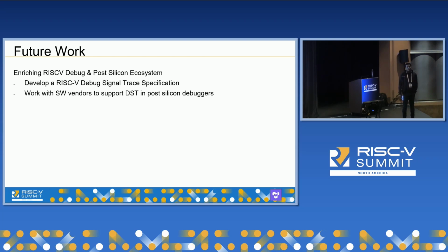But additionally, it also depends upon what compression logic you are using, right? So when we looked at the debug bus signals which are selected, we had three profiles: a profile with very active traffic, a profile with medium traffic, and a profile with low traffic, right?